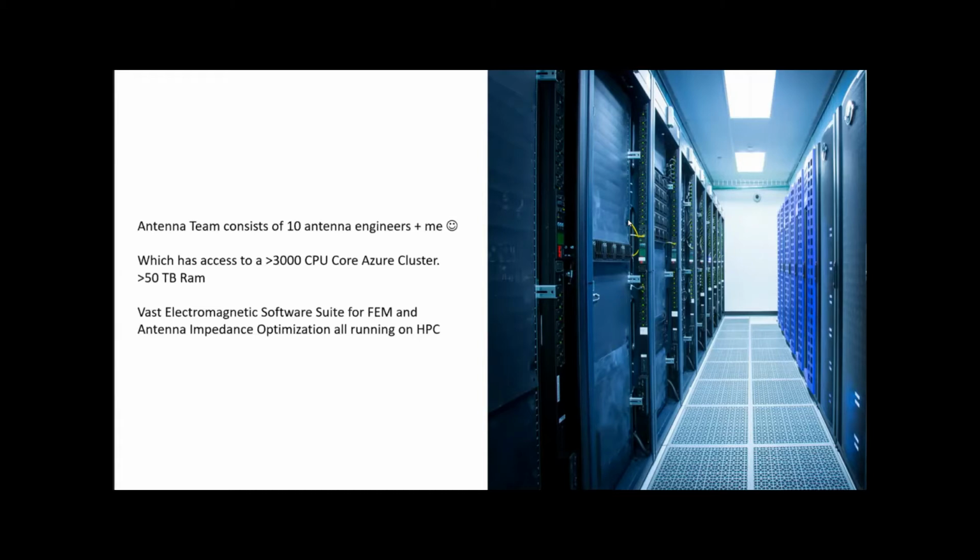We can split that up into individual simulations. Right? So I can run like 20 simulations, maybe they only use a terabyte each, or I can run one job using the whole of 50 terabytes. That's very rare, but those things can happen. And then we're using FEM simulation. So everybody will probably know ANSYS HFSS. ANSYS HFSS is probably the go-to tool for us in terms of simulation capability.